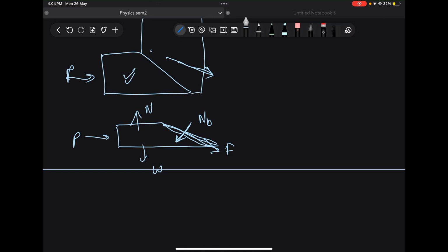Now friction, see why we are taking friction in the direction of sliding. This block is starting to slide in this direction, so the friction force on this block will be along this. This block is applying force in this direction, since the forces should be balanced because the body is in equilibrium. And in this way you can solve, and of course you can take F is equal to N perpendicular cos theta, and F is equal to mu N, and solve it in that way.